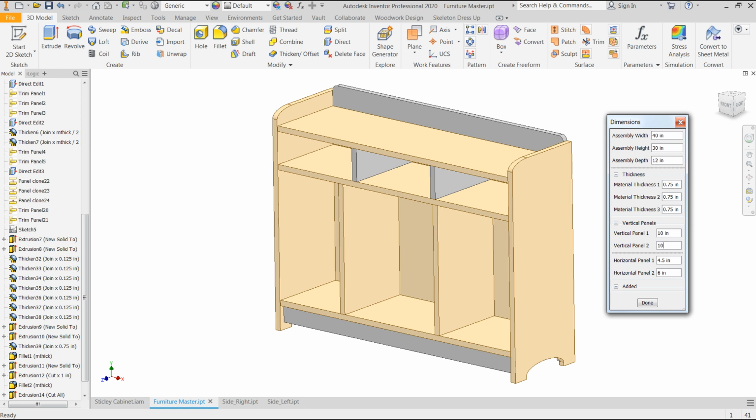So my entire model is now, at least at this point, able to be totally controlled parametrically, so that if I needed to create a family of these with different sizes, quick, easy dimensional changes would change my entire model. And as an Inventor user, if you have been using Inventor, you know all the drawings would update also.